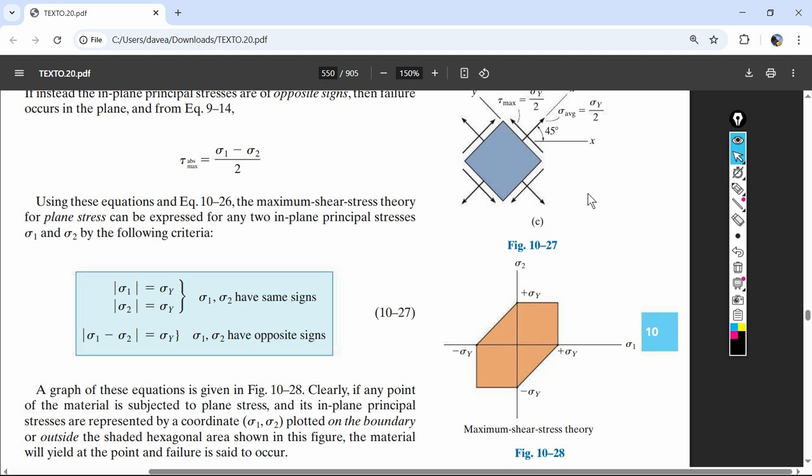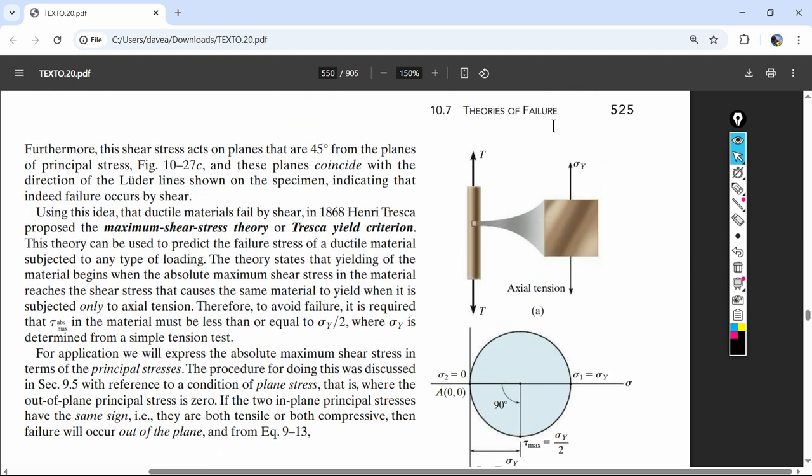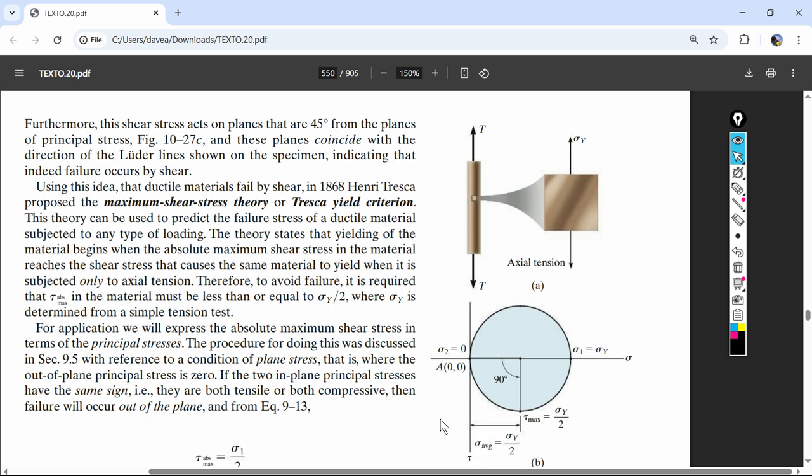So if my principal stress circle is on the other side, at 0 and negative, and we're in compression, if I just have axial compression in this direction and nothing in this direction, the circle goes this way. My principal stress in this in-plane direction is actually my first principal stress at 0. That's what tripped me up a couple weeks ago: your first principal stress is always the largest number, even if your other one is a huge negative number. So that circle is going to be there, and the radius would be your max shear.